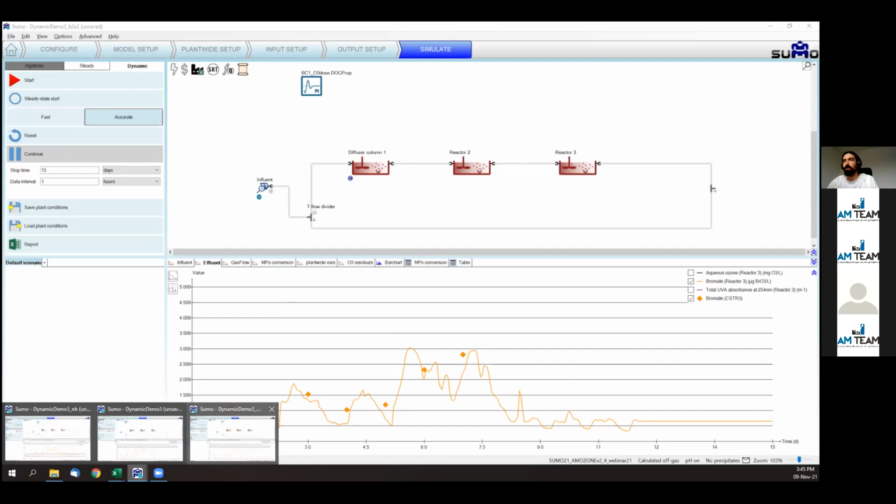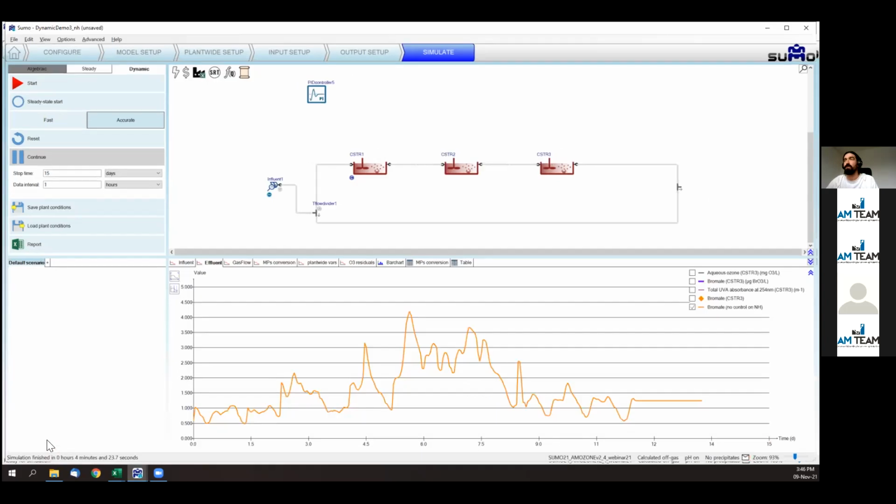But on the other hand, as we have been speaking about the ammonia, we can also have more fancy controllers and try to control bromate, optimizing the aeration at the upstream plant. So making sure there is a minimum ammonia concentration coming out, that we are not exceeding, of course, the effluent limits, but we can still have a sufficient action of ammonia on hypobromous acid.